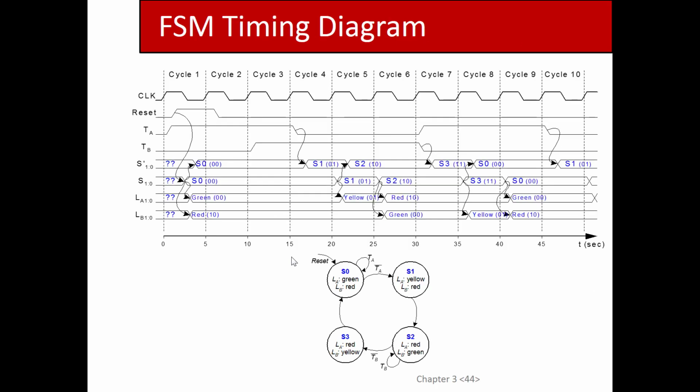When you're debugging or evaluating this circuit, you would do it in a simulator that would show a time scale view of what's happening. Usually the clock is at the top along with reset, and the clock just divides the operation into cycles. And then in each cycle you can see the transitions in the current state.